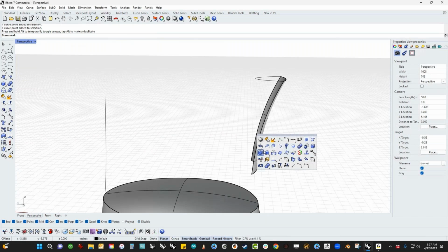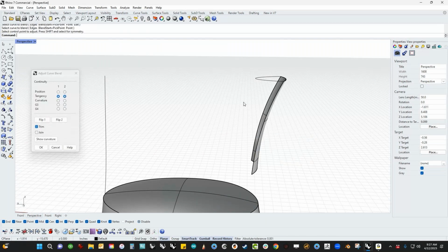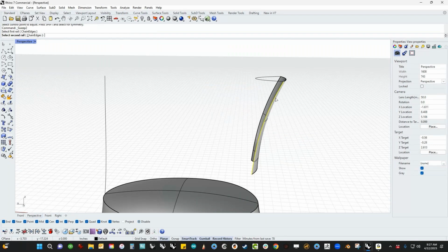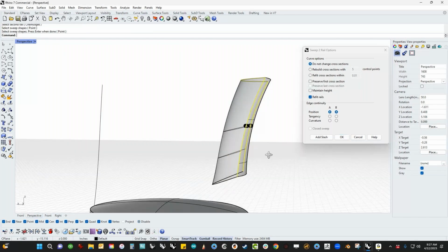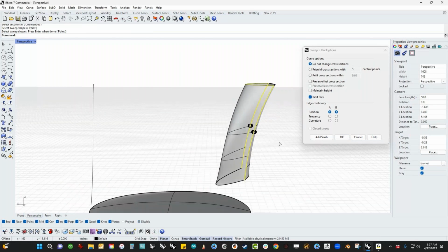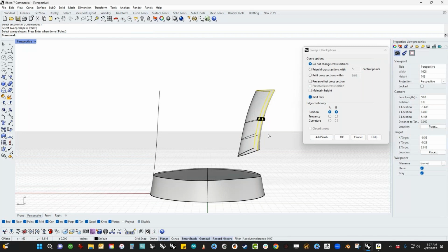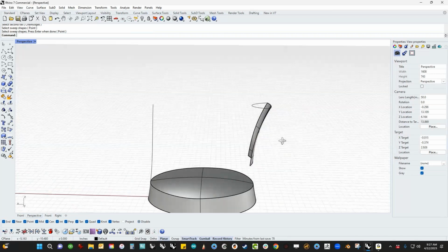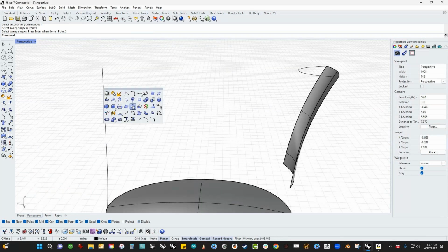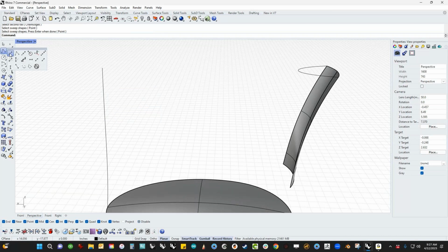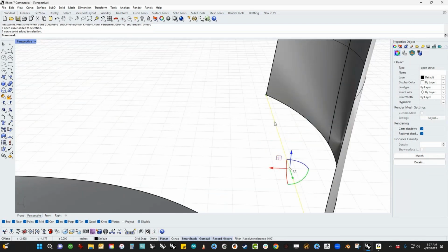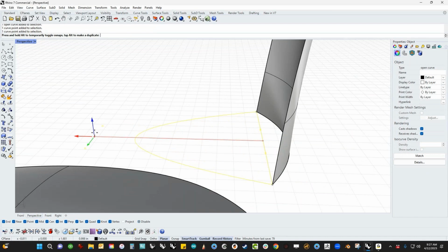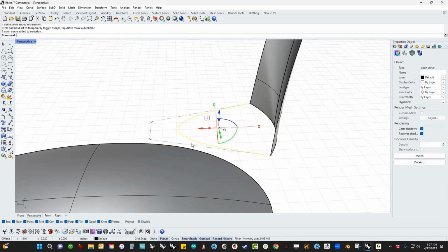And so once I get that set, we're going to go Sweep 2, pick the right tool, and I'm going to sweep that down like that, and can look at it and say it looks a little bit like a golf club handle, right? So let's add another shape at the bottom to get a little bit of variation top to bottom, because I actually want this to grow a little bit going forward. And so far, just to recap, we haven't done anything complicated yet. This is all something that if you've never tried Rhino before, this is super accessible.